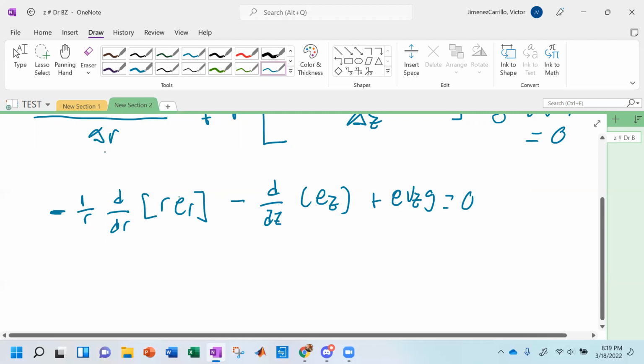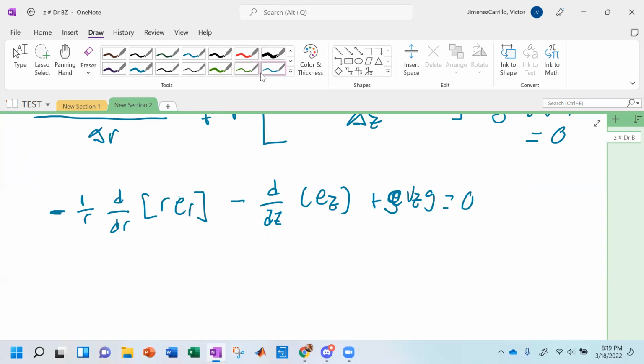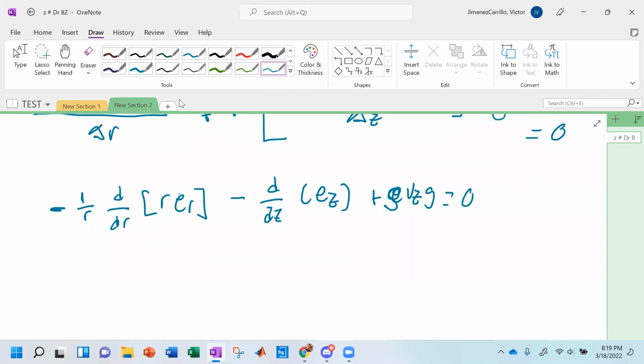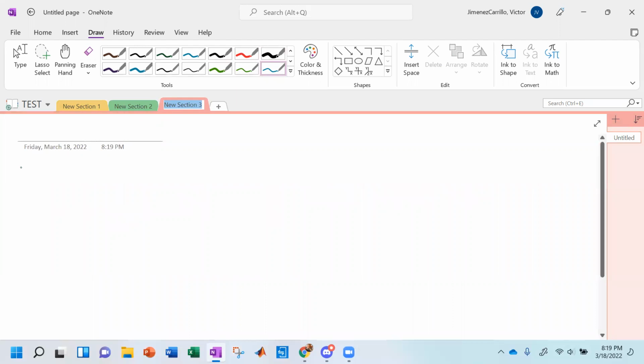Are those e's or rhos? All of them are e's, except for this one. I'm sorry, I'm not used to writing my rhos like that. Remember how we talked about in the momentum balance where we needed to replace momentum? We need to replace energy for every single one of these e_R and e_Z. So let's talk in steps. New page, because I like things clear and big. e_R is equal to tau_R_V_Z plus q_R. Since there is flow in the Z direction, does this term exist, the tau_RZ V_Z?